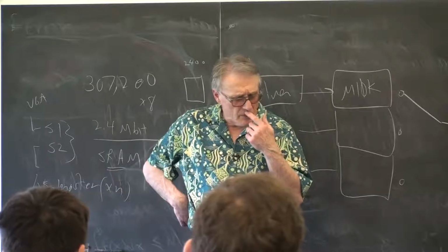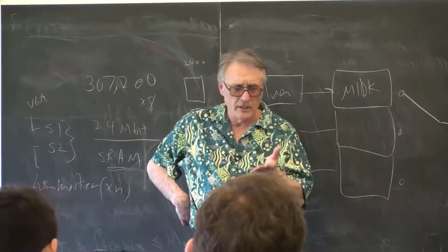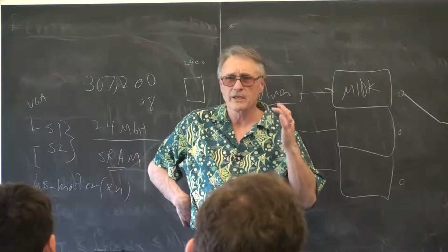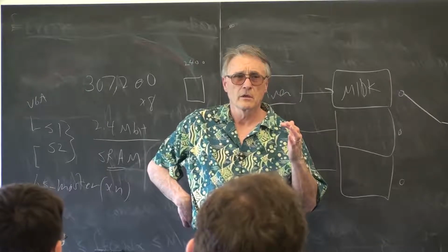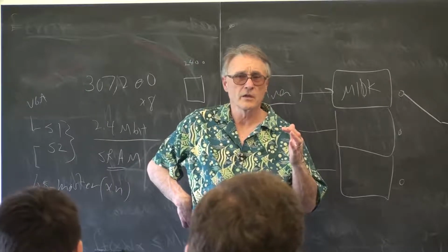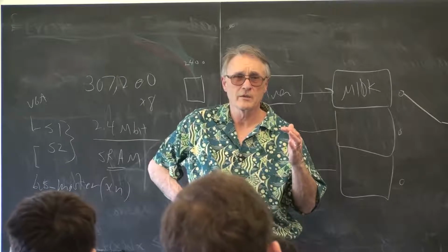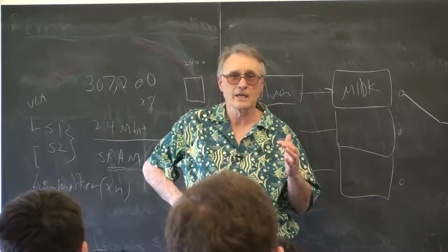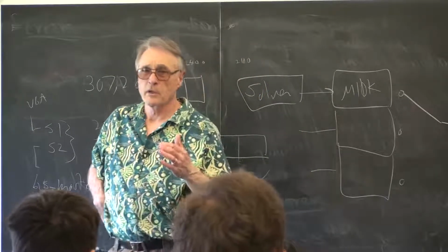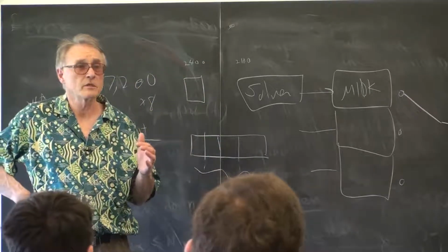There's somebody I think was using LVDS inputs to simulate an analog to digital comparator and do A to D conversions directly on the FPGA. That'd be entertaining because you get fantastic bandwidth that way. There is an A to D converter on this board. It's good to about 1 megahertz.